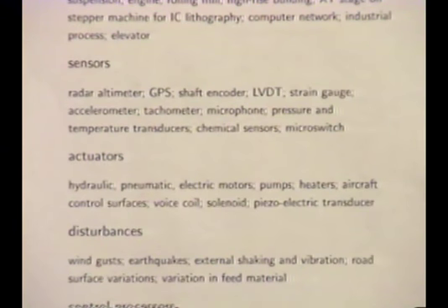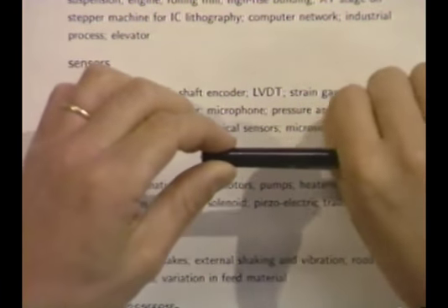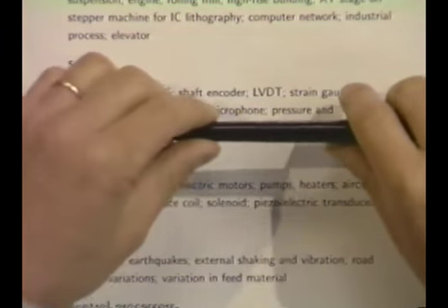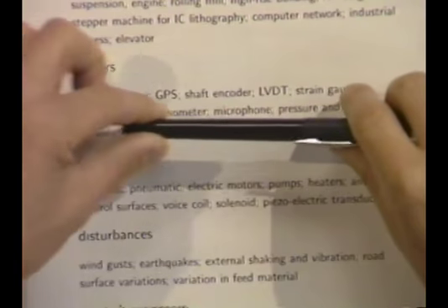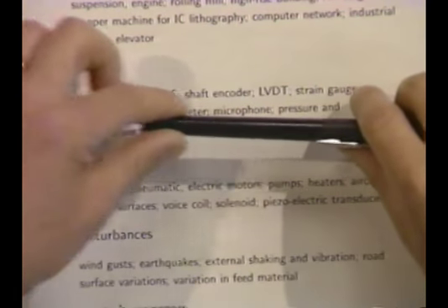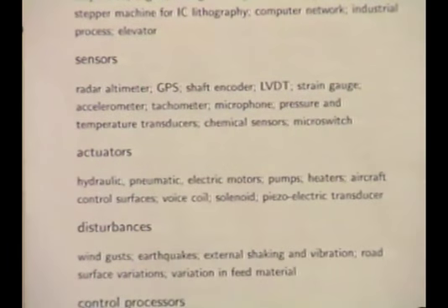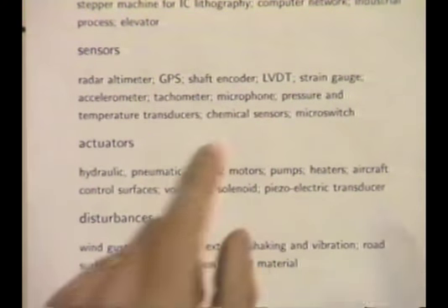It might be 8 bits, but it could also be 18 bits and give that pretty accurately. An LVDT, a linear variable differential transformer, will tell you, for example, how far extended a shaft is for a solenoid or something like that. This would be used for all sorts of positioning. A strain gauge is something that will tell you about very, very small displacements of mechanical things. It goes on and on.